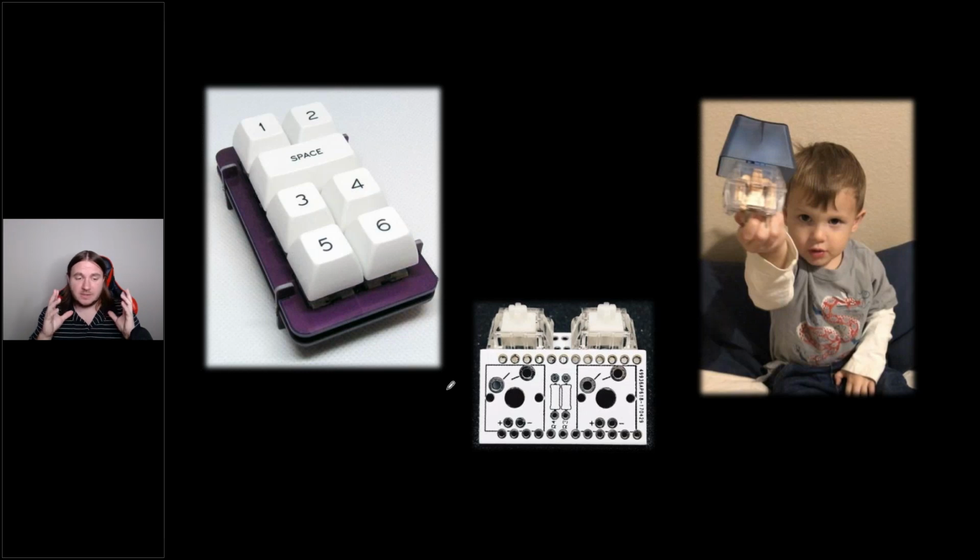And as long as you have a PCB that you're able to flash this on, you can use just a Pro Micro to do this. That's actually what runs many of my keyboards, is just little Pro Micros. You can just flash it on there and have whatever form factor you really want.